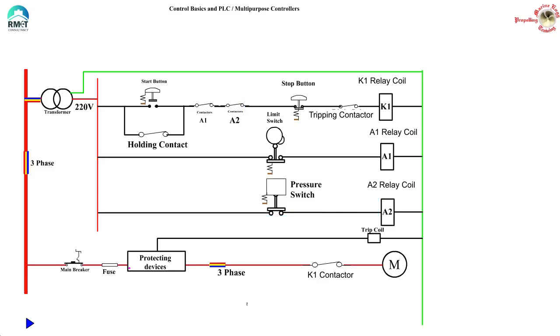So finally we have a motor which cannot be started if the limit switch is activated or there is a minimum initial pressure. In other words, the motor can be started only if the limit switch is inactivated and some minimum pressure is there in the circuit. These type of logics and many more form the basis of controls for many of equipment on the ships.